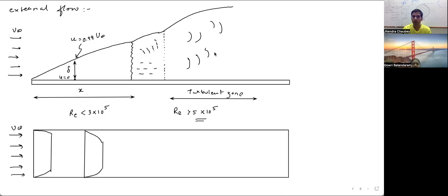With further propagation, this will shrink down and the layer will get more curvy. And there will come a point where only the centermost layer will have max velocity, and all the adjacent layers will have their velocity reduced, and ultimately it will be least near the surface of the pipe.